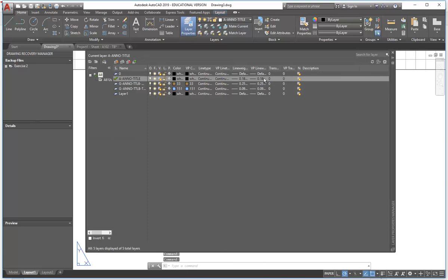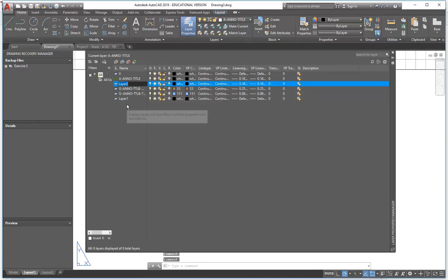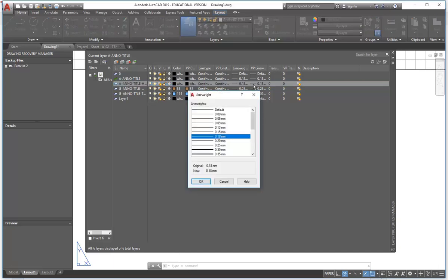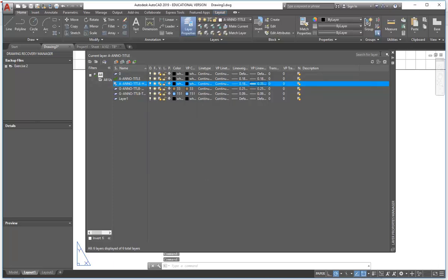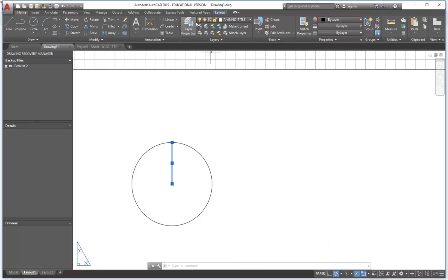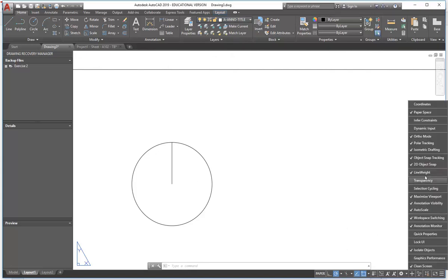Okay, so for that, I've got my 0.18 layer, so I can make another. Your radius was 10. Yeah. Title heavy. So it's just going to have a heavier line weight, so I'll do 0.35. I'm going to put that line onto the layer for the heavier line weight, but I can't see that yet. So I'm going to make sure I've got line weight ticked in the options, where you click on the lines to get all the customization options.